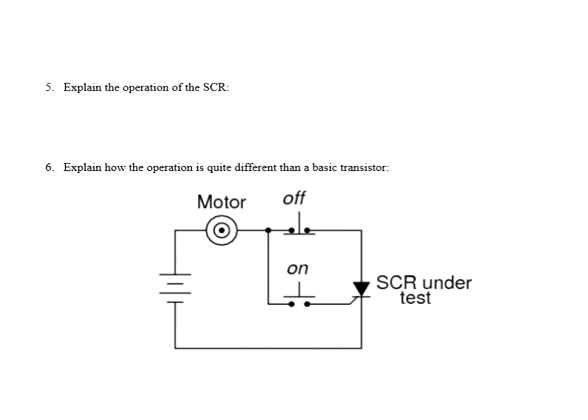So, here's a question for you. Once I turn an SCR on with a voltage on the gate, it will turn on. What happens when I remove the voltage from the gate? Well, nothing. It just stays on. That's the answer for the question, because I have to remove the current from the anode or the cathode to shut it off.